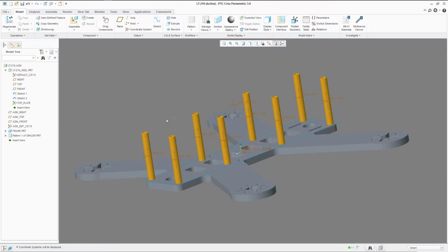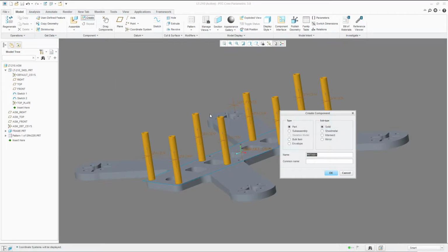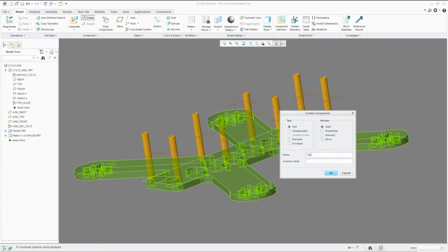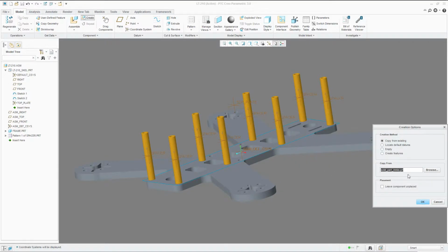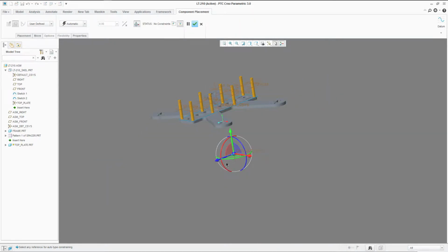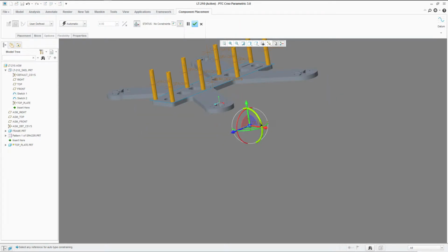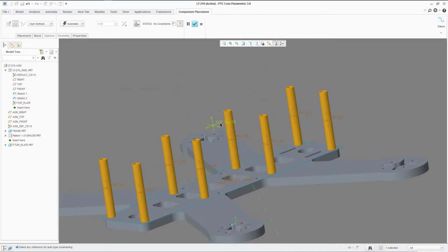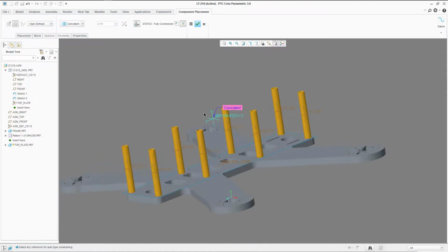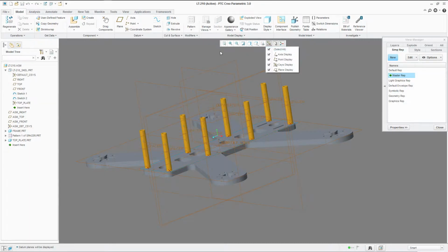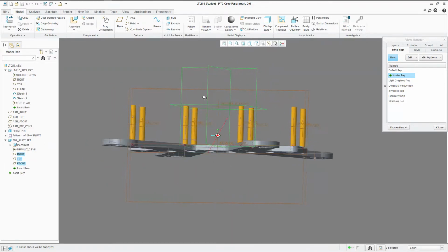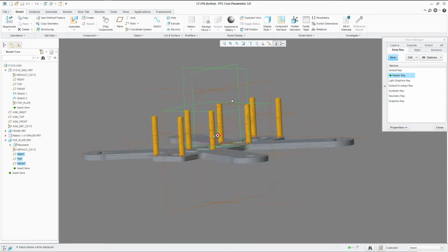Now let's start creating our top plate by creating a new part. Let's call it top plate. Okay, yes, and now we are going to constrain this coordinate system onto this one from the skeleton. Hit the OK, and you will see it's now placed on a nice spot.